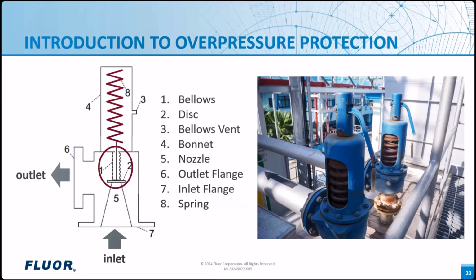By ensuring the relief device can pass the required flow, the PSV provides a mechanically self-actuated device that can prevent overpressure by diverting the excess flow to a safe location, typically a flare where the gases are safely combusted.